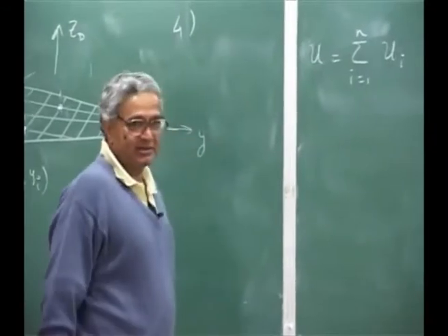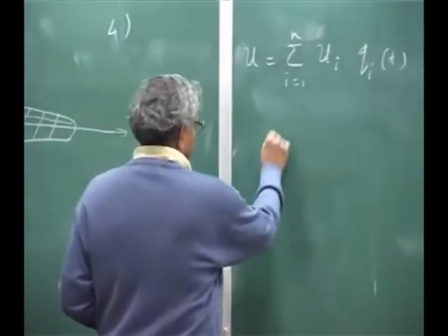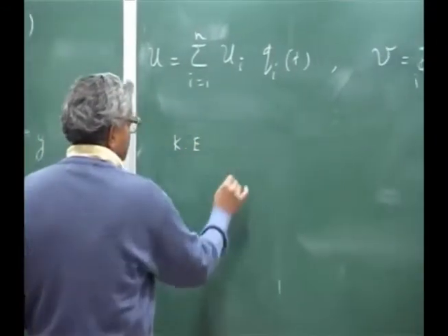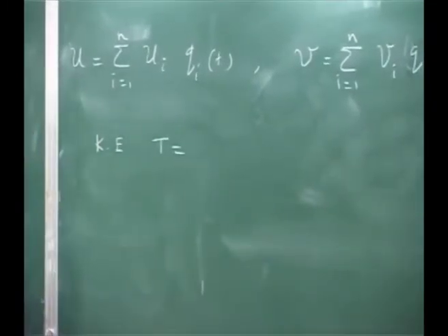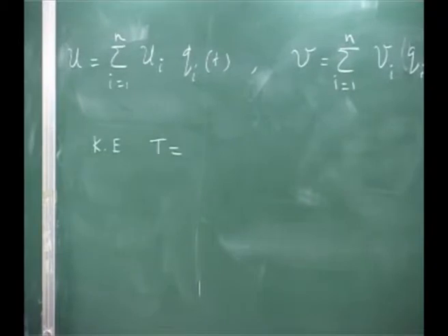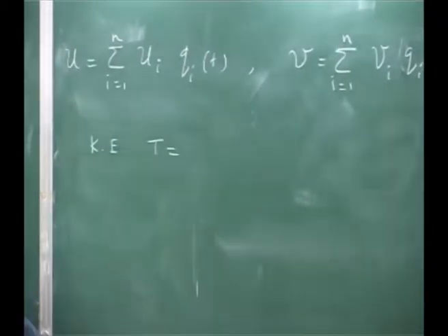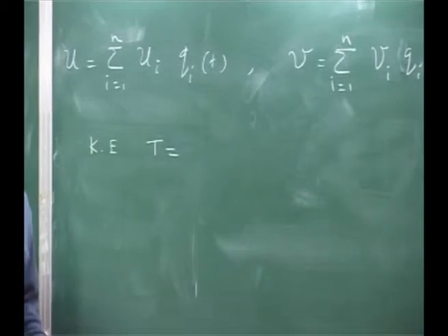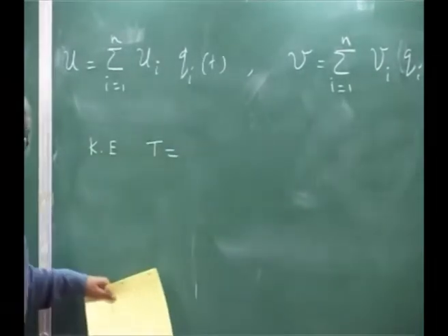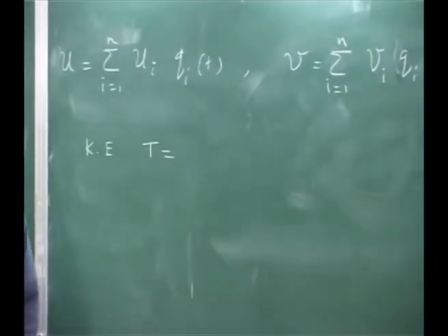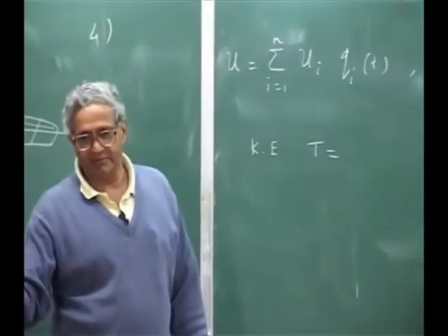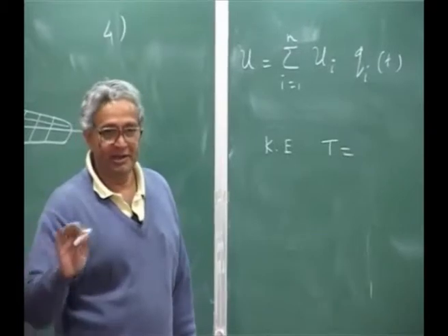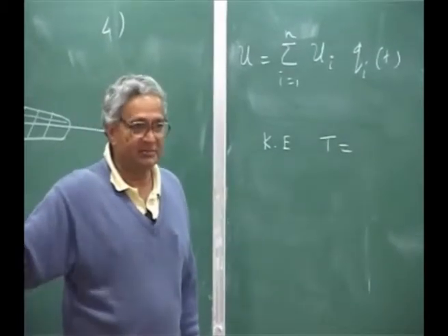Now you write the kinetic energy of the system. That means you are formulating your equation either by Lagrange's or by Hamilton's method. Please understand, you are starting from the beginning, writing the energy expressions: kinetic energy, strain energy, external work done, and applying Lagrange's equation directly, or Hamilton's, any one of them, and you will get the equation of the system.